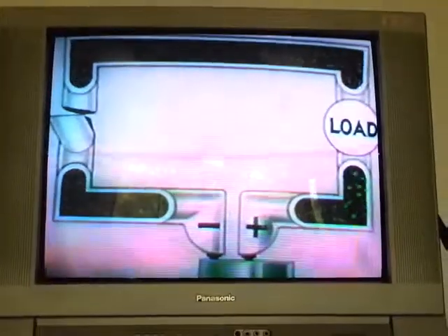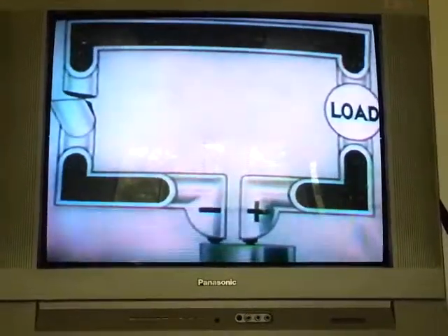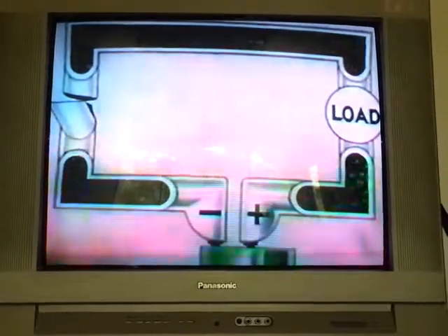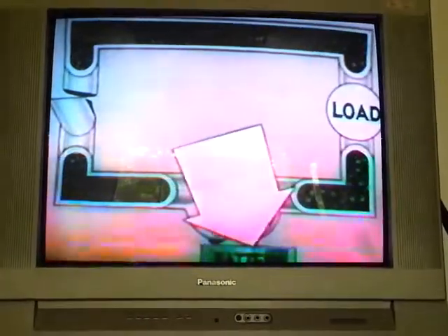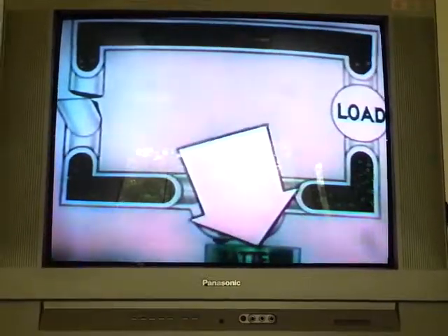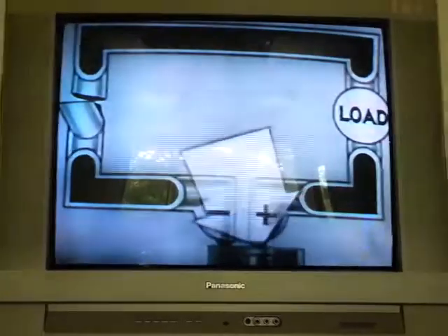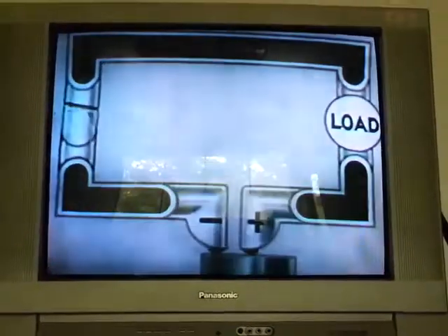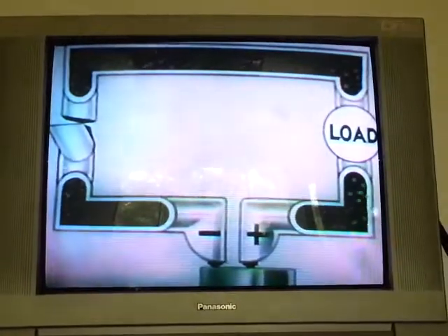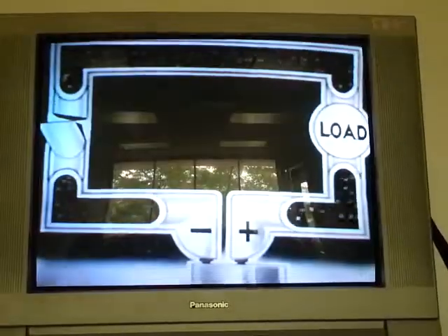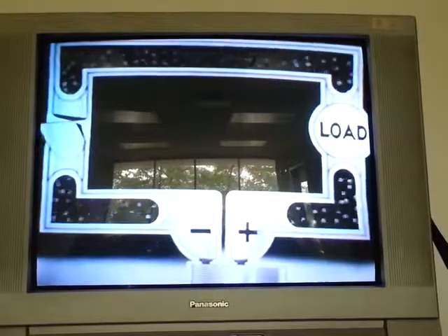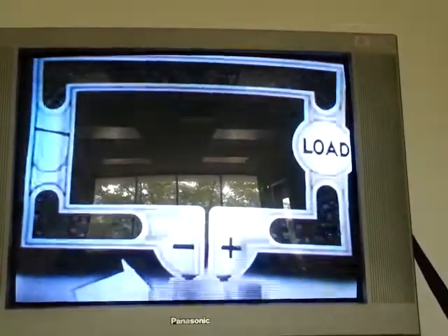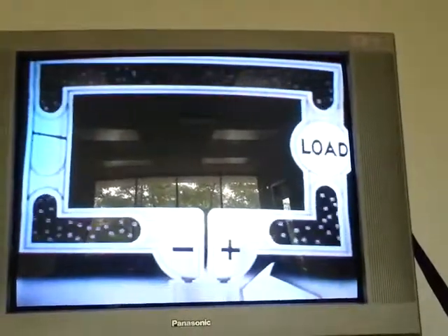A flow of electrons rarely occurs for any length of time unless some force is exerted on them to force them to move. Such a force may be applied by a battery or cell and is called the electromotive force. That is the force that causes the electrons to move. You must be careful to note that a battery does not manufacture electrons. They are already present in all of the parts of the circuit. It merely pushes them out of its negative terminal and collects them again at its positive terminal.